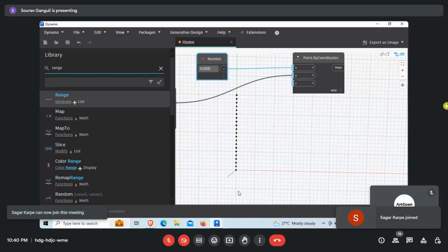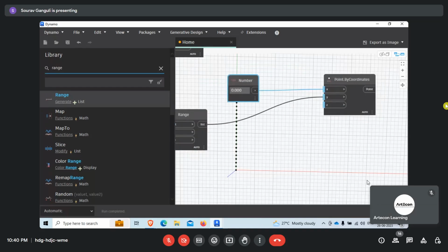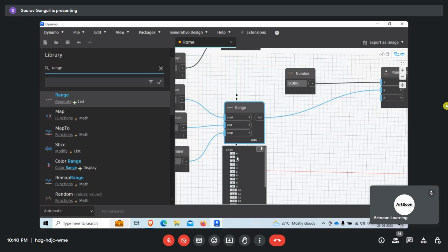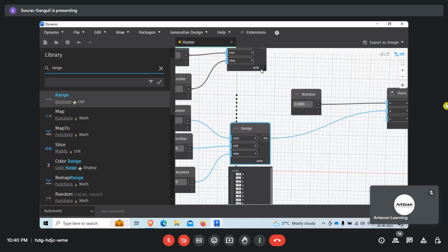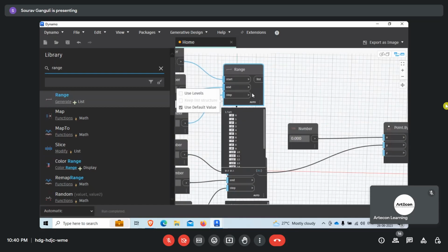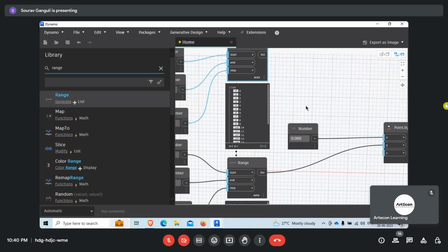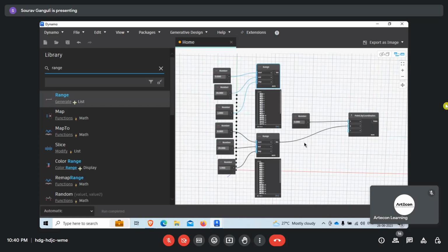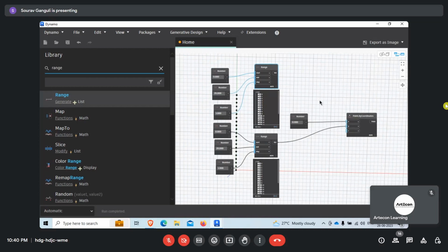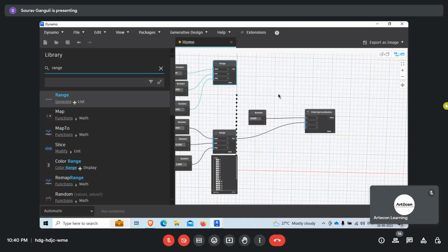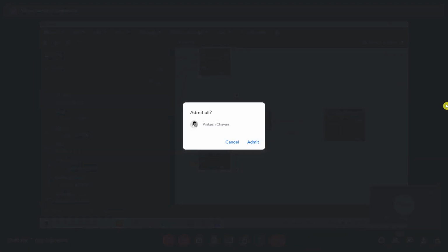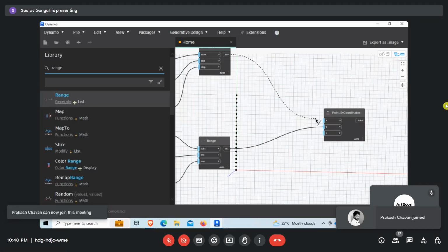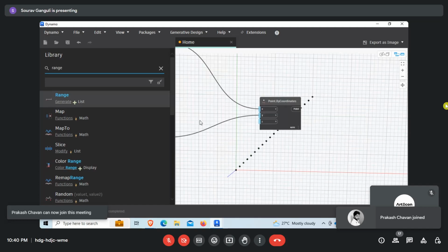But what I'm actually trying to create over here is a matrix which has every combination. If I have, say, 0, 1, 2, 3, 4 over here, I need to feed in a list which has as the first pair 0 0, then 0 1, then 1 0, then 0 2, 0 3, 0 4, then again 1 2, 3 2, 4 2, and so on. So in order to achieve all possible combinations, like 21 times 21, a 2D matrix of this, what we need to do is plug both of these lists in and change the lacing of this block.